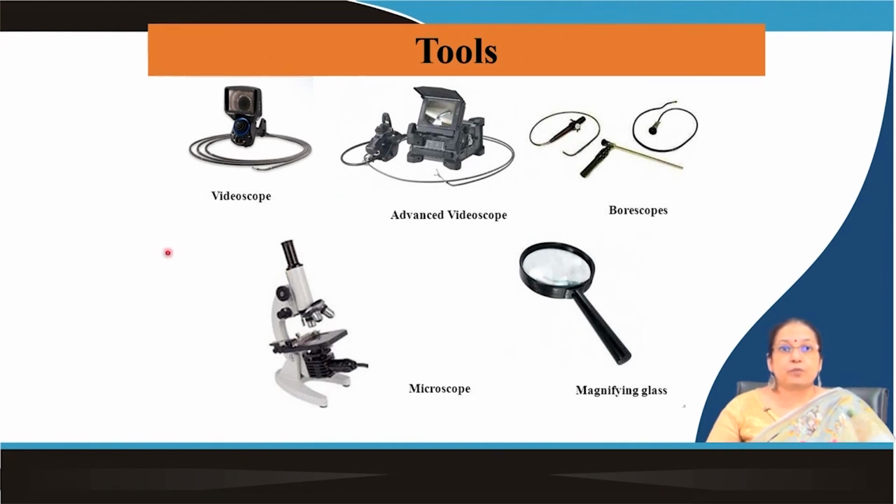Similarly, advanced videoscopy or a videoscope can also be applied to know the defects, and for a large structure you can go on recording the defects with a typical videoscope at low magnification, and subsequently analyze them at a later stage to know which defects are at which position. Those are very interesting tools for knowing the defect density, provided the defects are on the surface, are of very large size and dimensions, and are easily detectable.